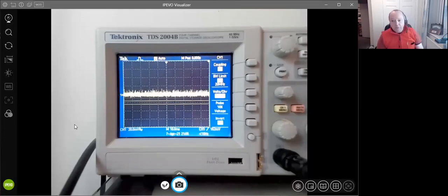I was having some noise problems, and I'm sure many of us in Cambridge know Steve Wiseman. I think he used to be a Makespace member, and he told me to put a 10 nanofarad capacitor in exactly the right place, pointed at the board where to put it, and boy, the problem just disappeared. So components in the right place is what you need.